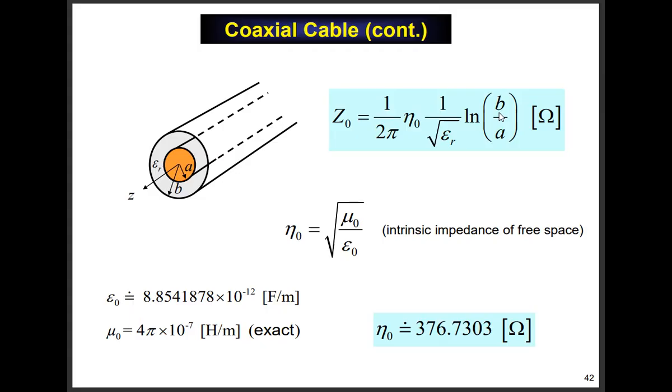So in your lab, when you connect a coax to the oscilloscope, it's probably still coax this big, right? It's not very big. If you look at those big coaxes running up cell phone towers that are carrying a high power signal, they may be that big around, right? Really high power coax. So you can make it much more high power and lower loss by making it bigger, but that has no effect on the characteristic impedance, which is the ratio of dimensions that determine that. Okay, so that's a practical note.